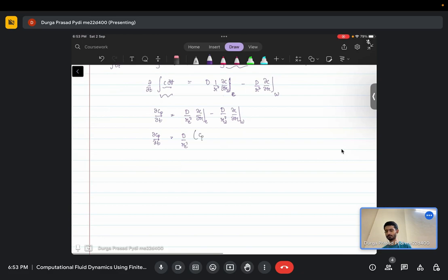So this is again very similar. On the east face you have C east minus Cp over delta r, and Cp minus C west over delta r. Maybe before doing this, I don't know if you're already familiar with implicit and explicit methods. How do you actually get these values? Again we have two different ways. We do it either the implicit or the explicit way. What I mean by implicit and explicit is, you have something like dou Cp by dou T.